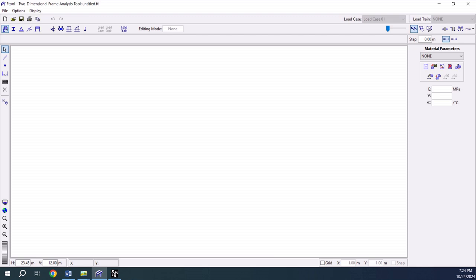Furthermore, the words static and kinematic are used when we refer to the solution performed using the force, also known as flexibility method, and the displacement, also known as the stiffness method, respectively. Static is used with the force methods where the unknowns are forces, and kinematic is used with the displacement methods where the unknowns are deformations, where the latter is universally referred to as degrees of freedom.